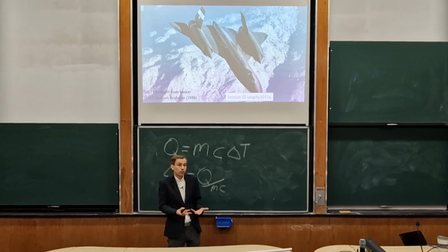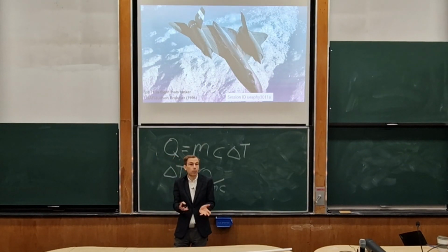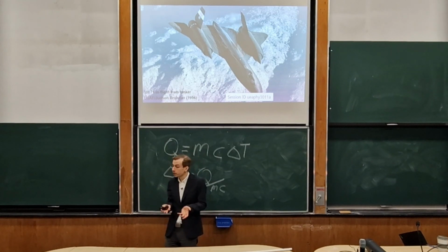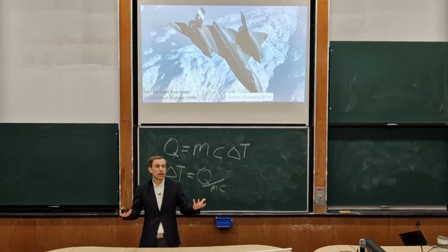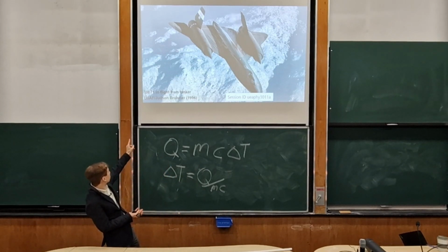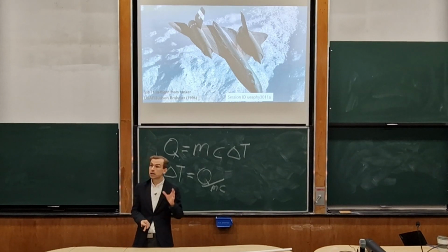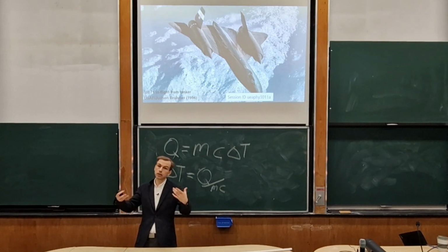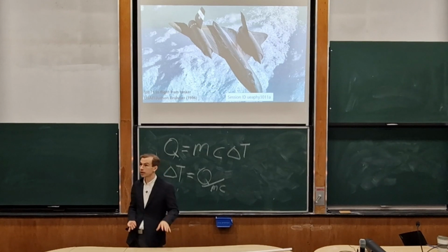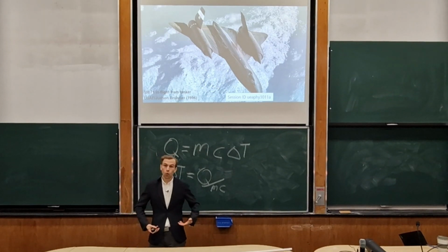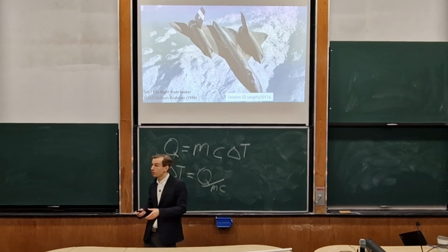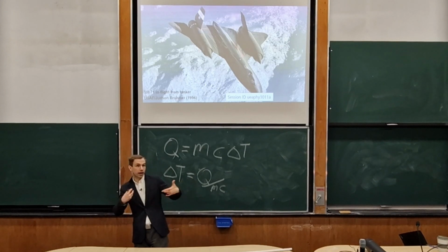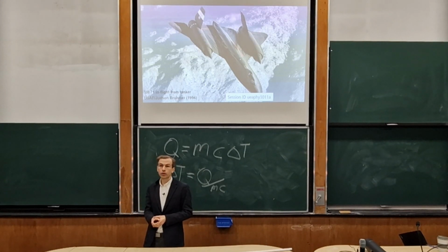So to account for this, the engineers actually had to leave gaps in the fuel tank. So when they filled up the aircraft on the ground, it just leaked out fuel, and it actually took off leaking fuel. And you can see that this photo was actually taken from an in-flight refueling tanker. So the first thing the SR-71 has to do once it's taken off is get refueled. And once it's flying along and the whole aircraft has warmed up a bit, those gaps in the tank close up and it doesn't leak all over the place. But it actually causes the aircraft to stretch due to this thermal expansion.